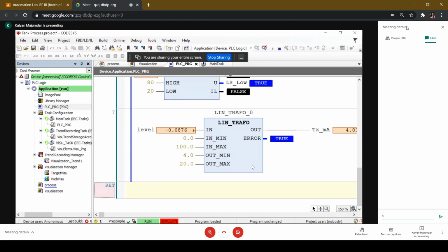So how do you implement a transmitter within this model? Remember, we have said that this is a zero order function. We are not considering any time constant. We consider the transmitter response almost instantaneous because we are neglecting the transmitter time constant with respect to the process. Process time constant is far, far larger. What it does is convert input level into an output current. So it is a form of linear transformation.